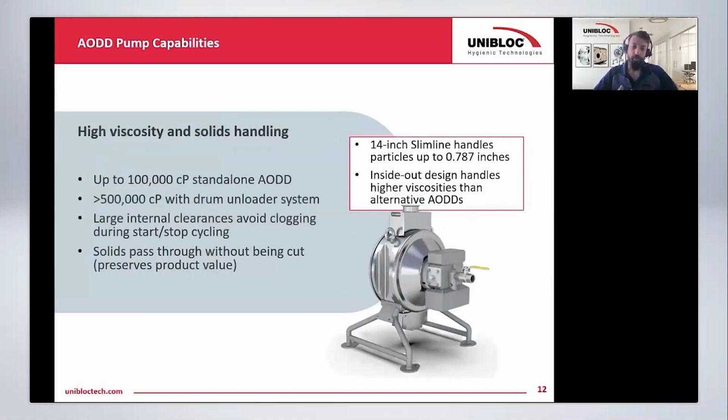The thickest product we've pumped with one of our diaphragm pumps is we had an OEM in Belgium that specialized in medical grade silicones for scar prevention and treatment. They needed a safe, clean way to move this 500,000 centipoise silicone elastomer from their 55-gallon drums to a mixing vessel. And so we were able to offer them a barrel unloading system that was able to handle the viscosity and their CIP and sanitary requirements.